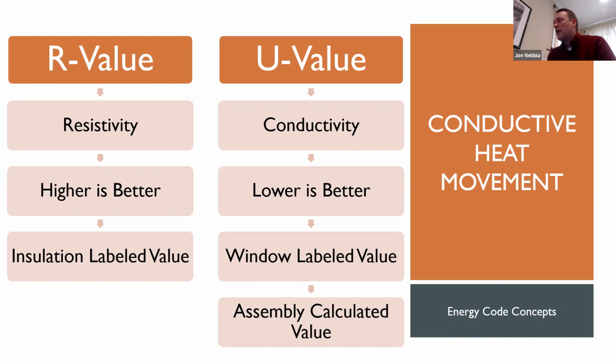So for example, if my insulation also air seals, I've heard some manufacturers or installers claim that this gives it a better effective R value, which is nonsense. It does not change the R value. It's a more efficient product because it does two things at once, but it doesn't raise the R value. So that's important from a code compliance point of view.